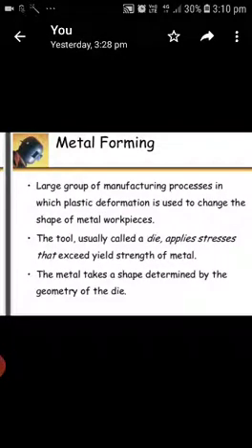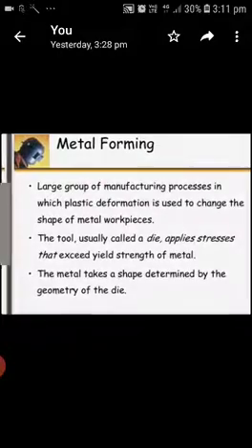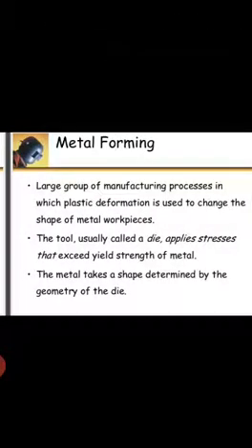Today we'll discuss the metal forming process in mechanical manufacturing. Forming, or metal forming, is a process in which the desired shape and size of the component is obtained through plastic deformation of the metal. The term plastic is used for the part of the behavior that results in permanent deformation of material without fracture. Plasticity is the opposite of elasticity.